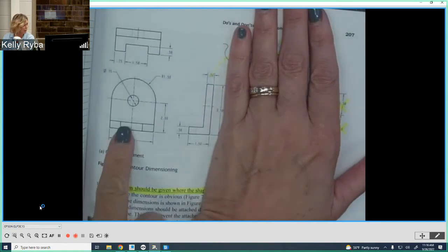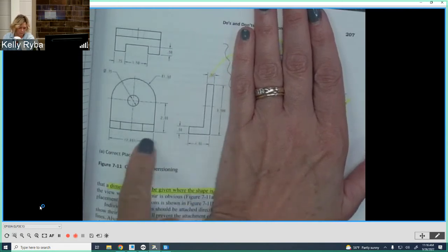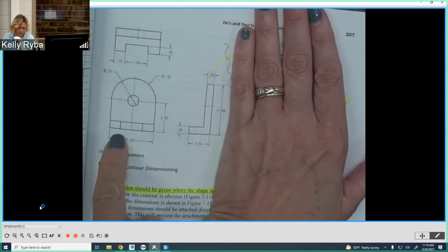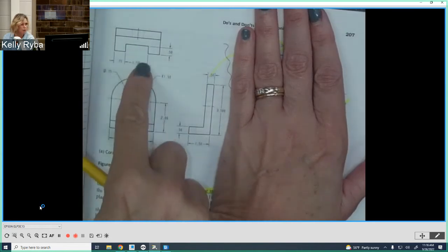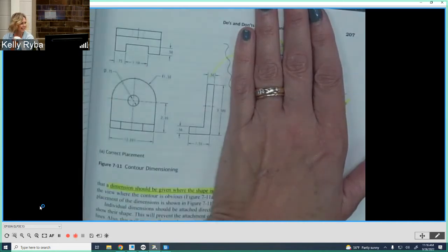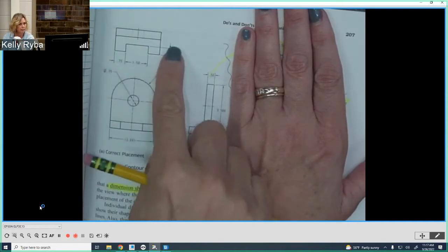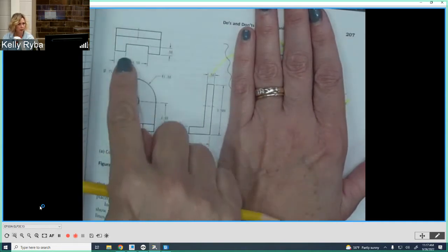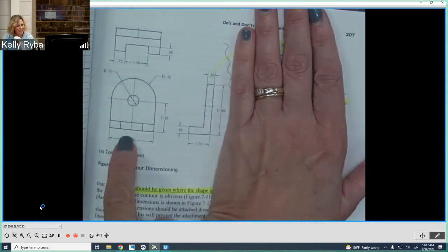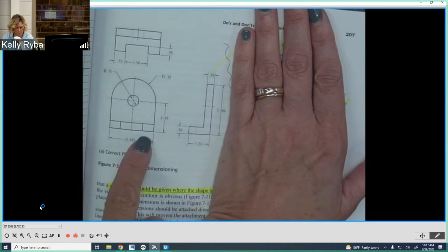So as we look here in the front view, we have this L-shaped bracket, okay? The front view right here, we see the two edges of the feet where there's a cutout. Notice that the cutout is dimensioned in that top view where we see it as that cutout, all right? So the width of that cutout, where it starts from one edge, how deep it is, all up here, all right? Now, you could maybe put it down here because we see this edge as 3/4 of an inch, for instance, or the width.